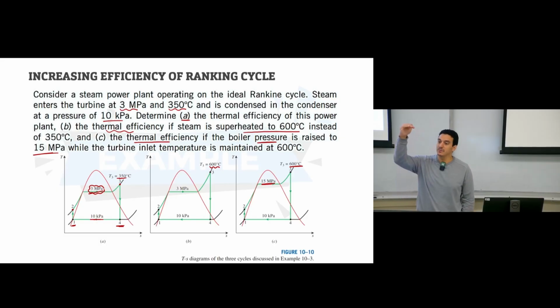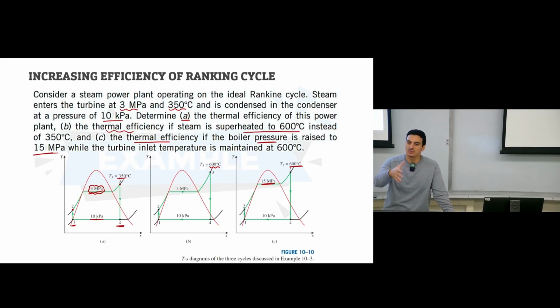As we said, the maximum efficiency we can obtain is the efficiency of the Carnot cycle. And again, in the example in the video, you can see that we calculated the efficiency of the Carnot cycle, and it was almost 45%. So we have the maximum efficiency, it's 45%. Based on the conditions of the example in the previous problem, the efficiency was 26%. So we still have plenty, about 20% of efficiency, that we can try to increase.